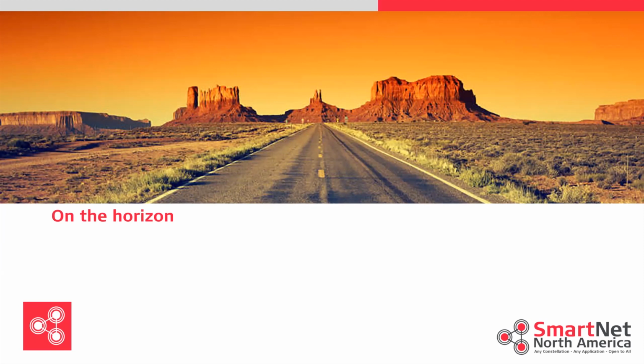Does this mean the coordinates we receive from the RTK service will change? Whatever broadcast you're using, if you don't change a mount point, the broadcast coordinates will change. If you're using the IGS mount point, you would actually have to change to the new ITRF mount point for it to change.